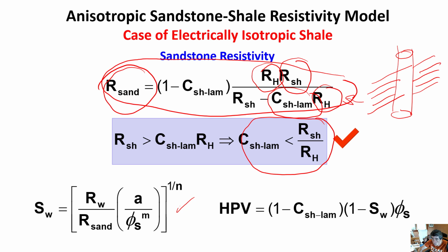And when we did the analysis, we did not calculate the dip, and therefore we did not correct the measurements that were perpendicular to the borehole. We have to correct them to be parallel to bedding plane, which means that we have to rotate a vector. But suppose that we did not do that rotation and the angle was not negligible, then because of that we might have a problem like this.